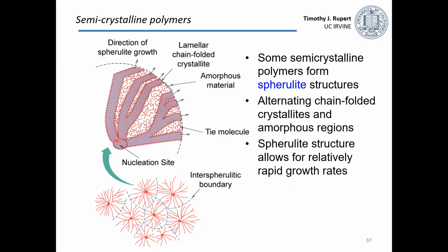There's some sort of aligned structure in all of these spherulite growth regions, these lamellar regions, but there's also that amorphous region in the middle of it. If we look at our larger materials, we zoom out, what we would see is that these crystalline regions nucleate in a bunch of random places, just like we learned about in phase transformations of metals and ceramics, and that they grow out and they'll end up eventually hitting each other. So we can identify boundaries between these different spherulite regions, okay?